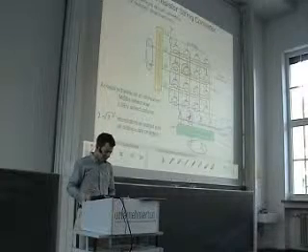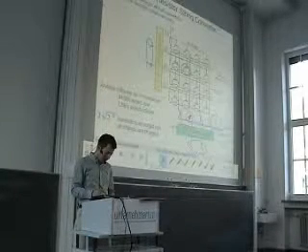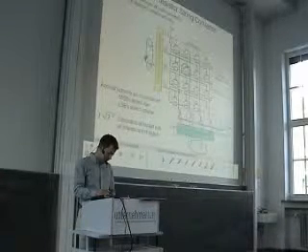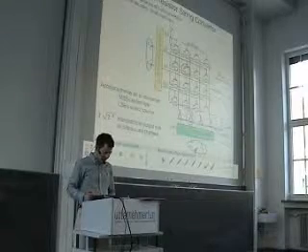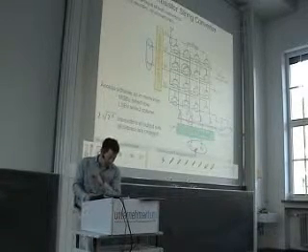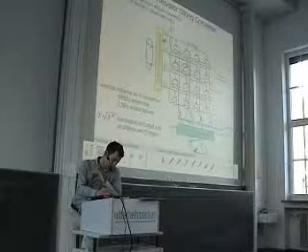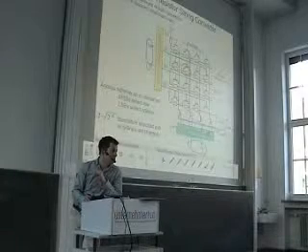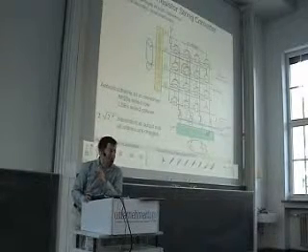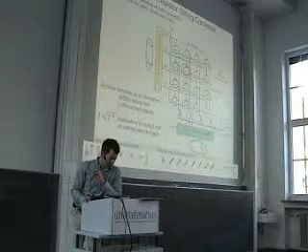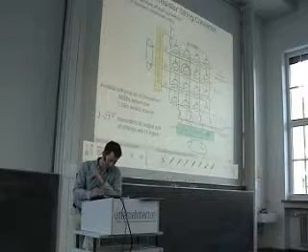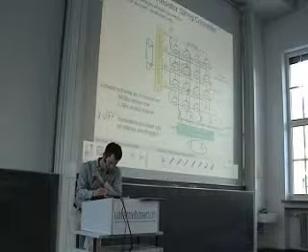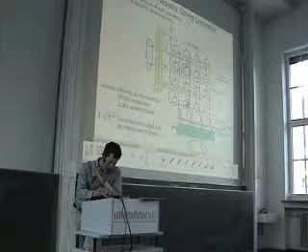So the advantage here is we bring this down by a factor of 2. As I said, we have here only half the number of bits and here half the number of bits. So this means that we reduce the number of wires with the square root, and the number of transistors that is actually connected to a certain line is also reduced, because here you can see in this column, for instance, we have connected only 4 devices.